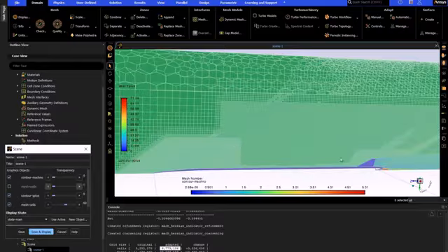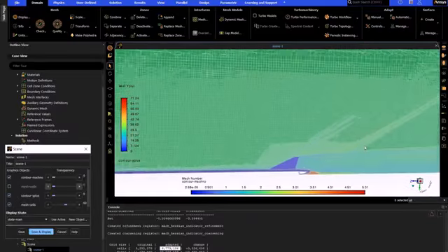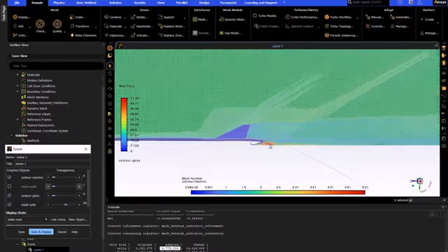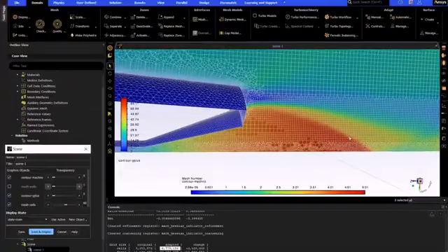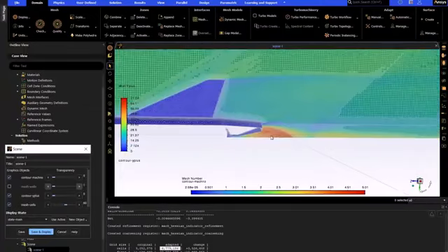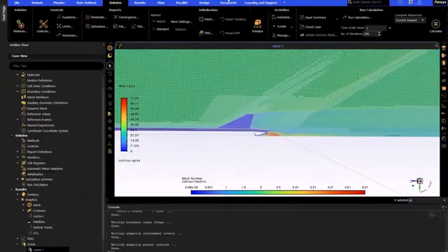Displaying the mesh scene again, we can see the refined regions where there is increased cell count. Specifically, these are regions with a high Mach number gradient, such as shocks and the jet exhaust. Finally, we'll rerun the simulation to calculate the refined solution.